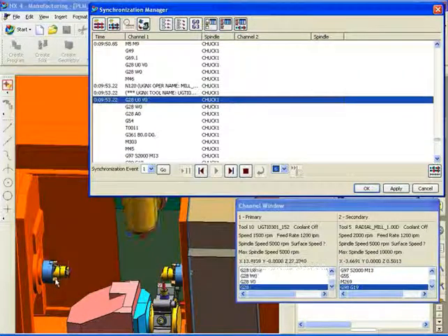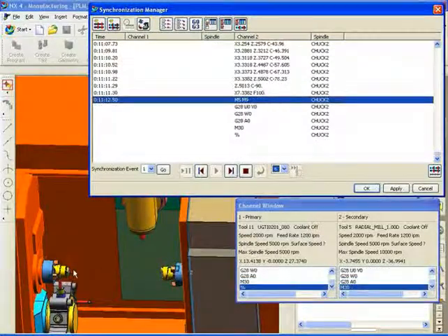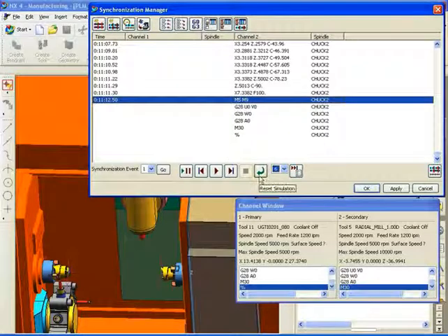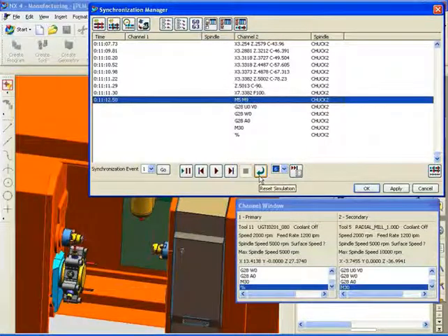We're going to use a large tool. If it were over here, it'd be hitting this chuck every time the chuck moved around. Now we're going to do our work on this end, park the spindle, and then come back. We have that level of control with the synchronization manager. This allows us graphically to have a nice layout to be able to control and use and predict what's going to happen on these very complex multi-spindle, multi-turret, multi-head machines.